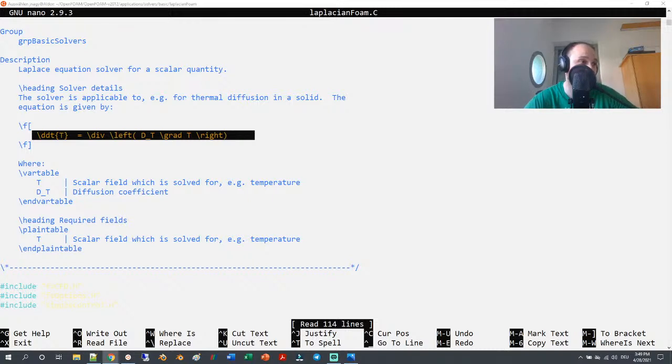Which meshing utility do you use most, from the perspective of commercial geometry, and which do you recommend? Open source or commercial mesher for OpenFOAM solvers. So I use snappyHexMesh or cfMesh, or extrudeMesh is also something that I use extensively if the geometry can be set up so that I can extrude a 3D mesh into the geometry, or if it is a 2D geometry, then I also use extrudeMesh.